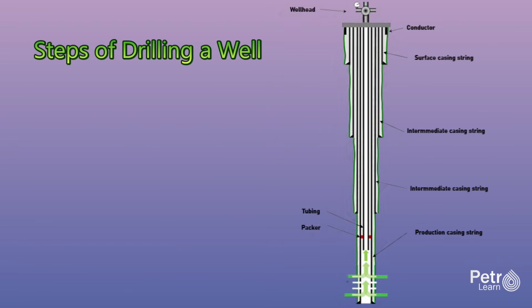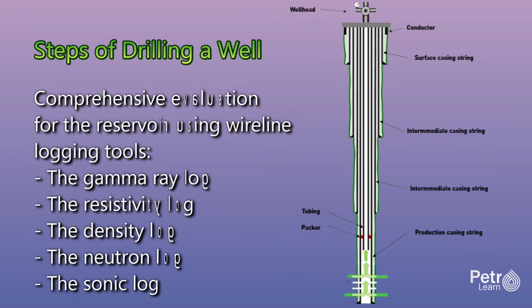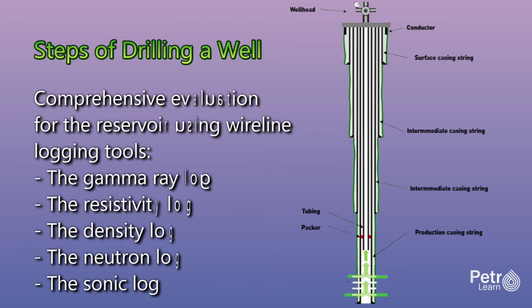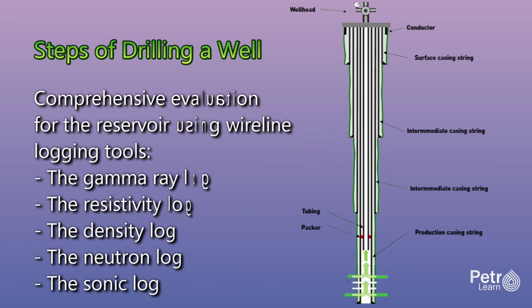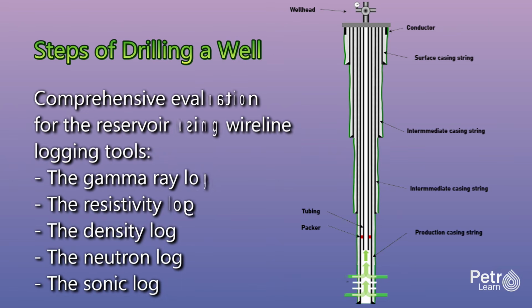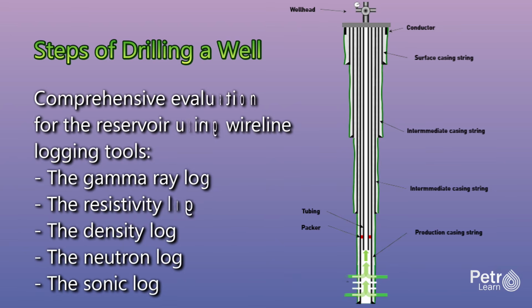When the well reaches the target depth, typically determined by LWD data showing that the planned reservoir interval has been penetrated, drilling stops and the comprehensive evaluation phase begins. The drill string is stripped out of the hole and wireline logging tools are run. Wireline logging uses an electric cable to lower instruments into the well. The cable, which may be 20,000 feet long, has conductors that provide power to the tools and transmit data to the surface. Multiple logging runs are made with different tool combinations.